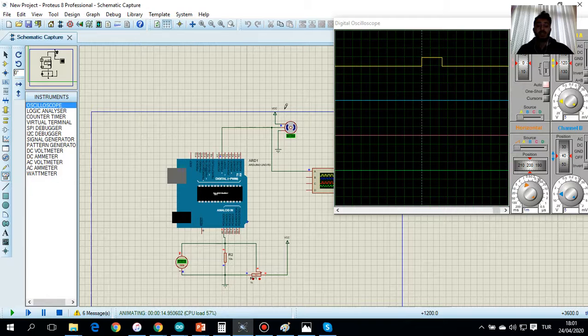Running the servo motor is really important because it is an essential motor type, and we always use it in robots, robot arms, and other kinds of projects where we need precise angles, because as you see we can have whatever specific angle we want. That's why in precision projects we always use servos. That's why knowing how to run a servo is going to be valuable for everyone when we do that with the analog signal through the PWM module.